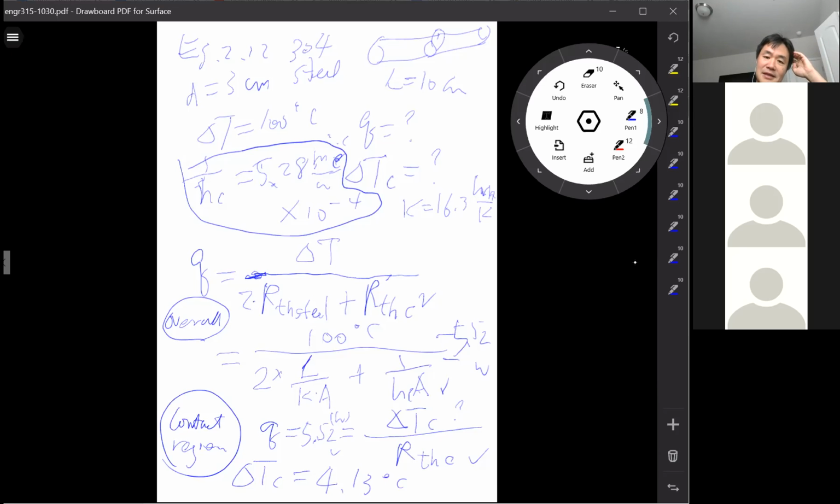I think that's one of the goals of introducing the thermal resistance idea, because when you calculate conduction, convection, and radiation, their equations are all different, which increases the complexity when you solve problems. But now you look at this equation, all the different information has been included in the resistance, which is a coefficient. The overall equation will be simple and always the same.